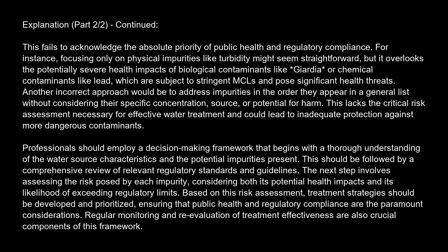contaminants. Professionals should employ a decision-making framework that begins with a thorough understanding of the water source characteristics and the potential impurities present. This should be followed by a comprehensive review of relevant regulatory standards and guidelines. The next step involves assessing the risk posed by each impurity, considering both its potential health impacts and its likelihood of exceeding regulatory limits. Based on this risk assessment, treatment strategies should be developed and prioritized, ensuring that public health and regulatory compliance are the paramount considerations. Regular monitoring and reevaluation of treatment effectiveness are also crucial components of this framework.